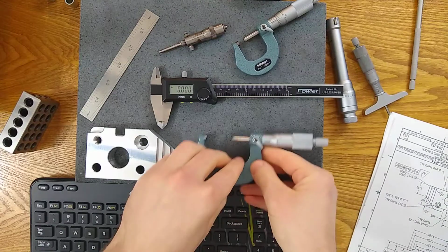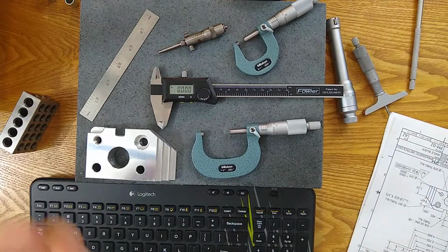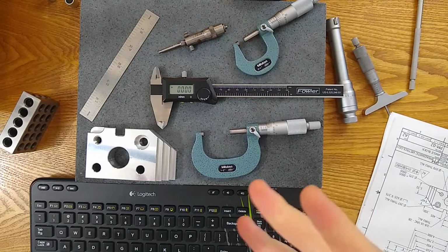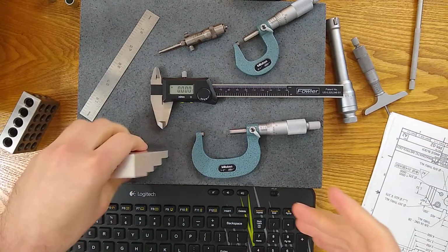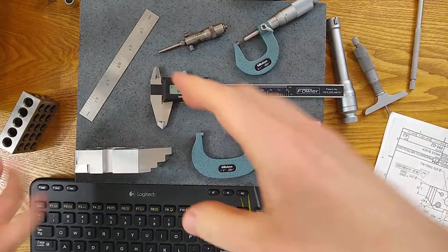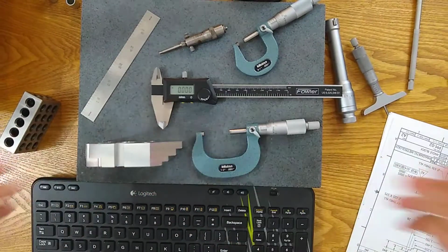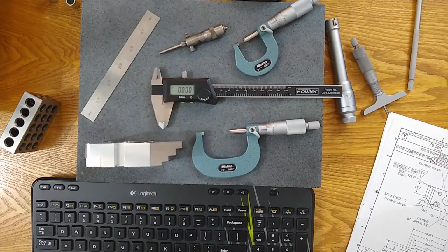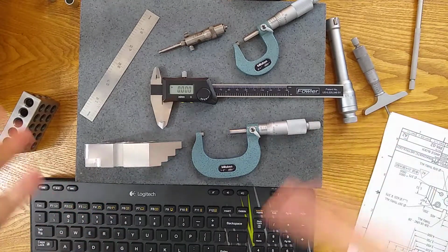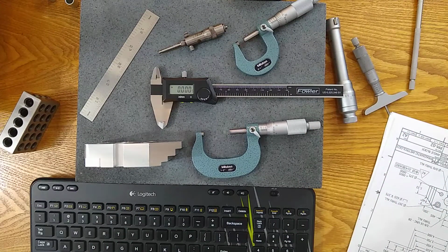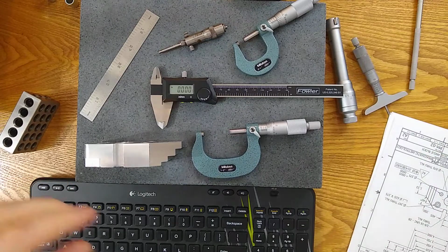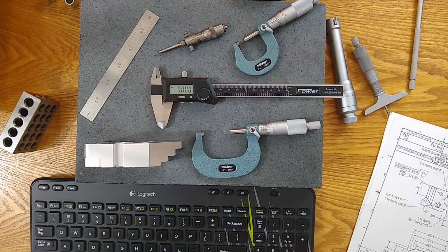Could be a micrometer. You ask yourself, do I need to fixture the part to use this tool? Do you need to set up on a rock? Do you need clamps? Do you need to hold it a certain way? If you are going to need to do that, maybe because you're using a height gauge, you have to do this stably and repeatably. So if your fixture is not stable or repeatable, you're not going to get the same measurement again. And if you can't do it again, you can't really trust any of your measurements, can't verify it.